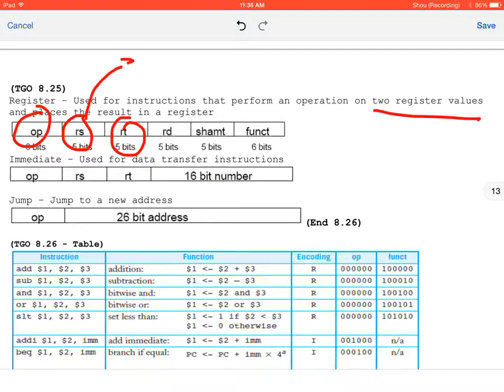This 5-bit value is translated into a 32-bit value, so you have a 5 to 32-bit decoder. One of the lines is on. That one value that is on is the line that goes into your dual read SRAM. If you have 2 values on from 2 32-bit selections, that's where word line A and word line B come in, and that permits your dual read.